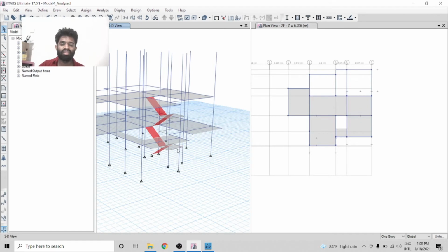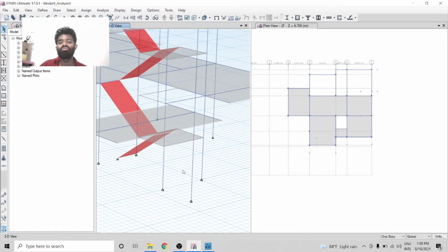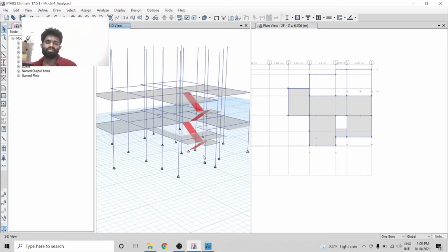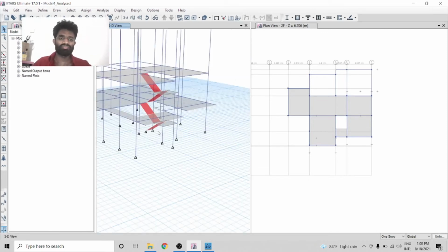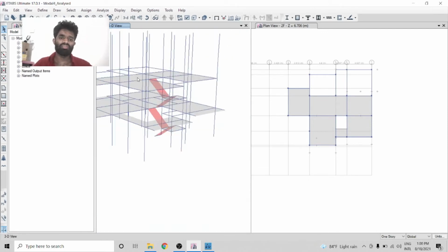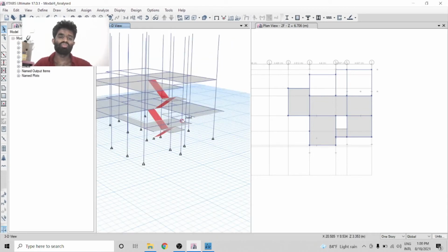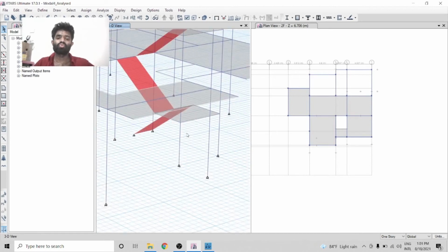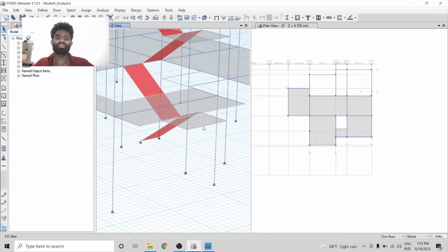We are trying to load this landing to the wall part below. So it should be a load bearing wall here. We have to indicate that in the drawing. Otherwise, later the house owner, if he decided to demolish that one, everything will collapse. So be careful about that when giving the instruction to the owner or giving the instruction in the drawing. So you have to clearly identify this one as a load bearing wall. Otherwise this will not last long.